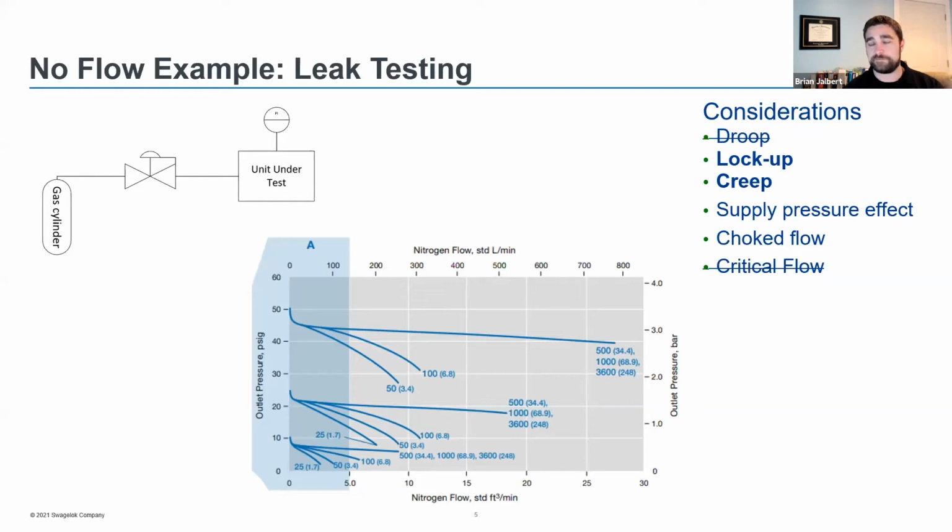Every single time that it fills up to that set pressure, it's going to shut off. So with a leak testing application, you want to look at a regulator with a hard seat. It's going to give it a little bit more longevity, especially if it's leak testing to a high pressure, which is generally what most of us are doing. You're doing a high pressure test to make sure it's going to hold in the environment that it's going into. So PEEK seats are great. PCTFE seats are also pretty useful for that.